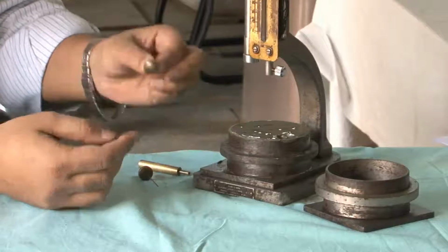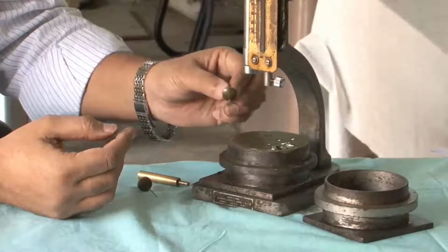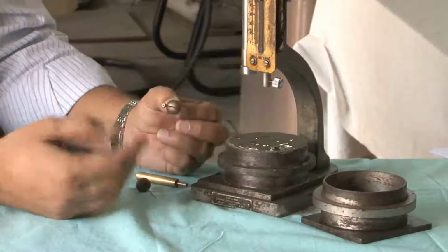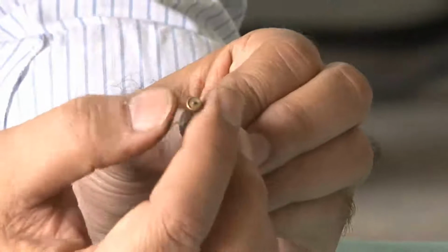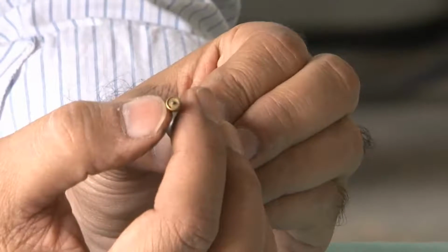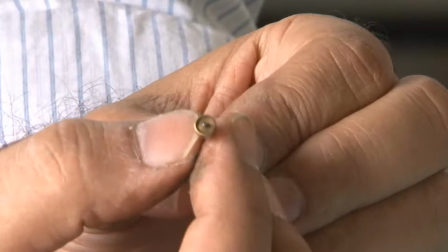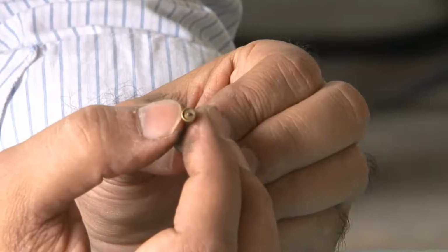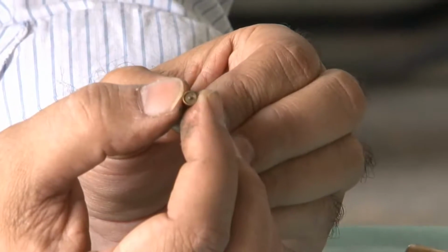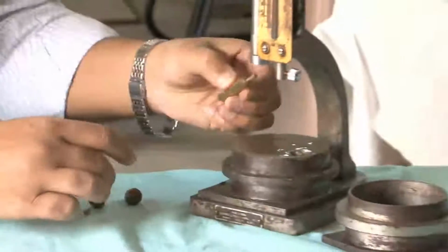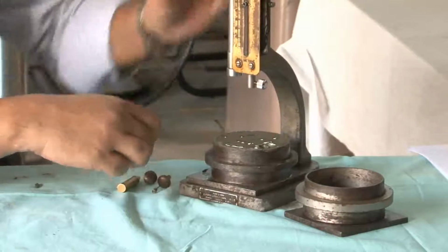What happens, especially the final setting time, is a very interesting experiment, where we wait for the cement paste to set to the extent that, if you notice carefully here, there is a needle which is penetrating just outside the round surface here. What we need to ensure for the final setting time is that the needle at the center should make a mark and the outside surface should not be visible. So, once we fix these plungers, either it is this one here or it is this one or it is this one, we try to use this